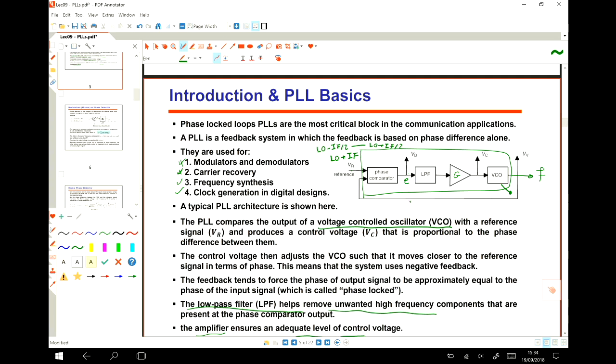And then we try to change this error function to 0 in a kind of loop. This error function again applies a voltage to this VCO. The voltage of this VCO changes, the output frequency changes, again the error changes, and so on, until the error function reaches 0. When the error function reaches 0, it means that the output frequency and the input frequency are the same, or the output phase and the input phase are the same. No difference. Okay?